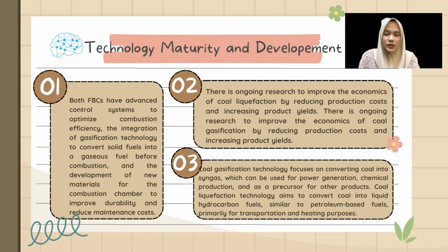For application, fixed-bed combustion technology is suitable for small-scale applications and certain industrial processes, while fluidized-bed combustion technology is employed in larger-scale power generation and waste-to-energy facilities. For example, the production of electricity from coal-fired power plants, and production of heat for industrial processes such as cement production and steel manufacturing.